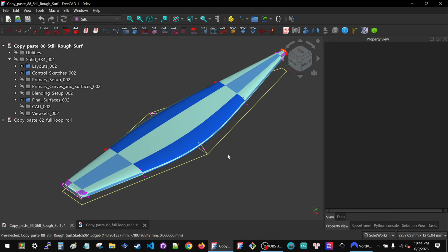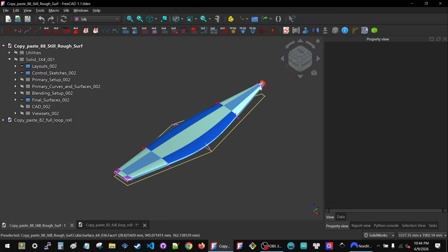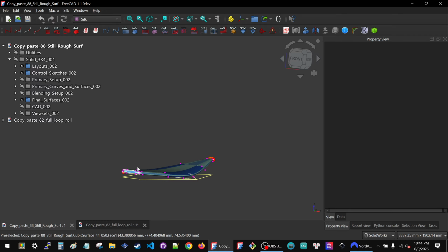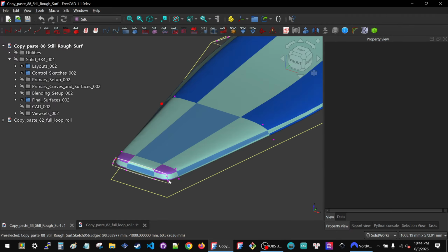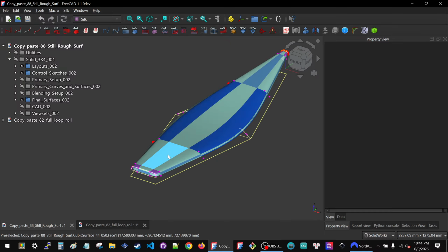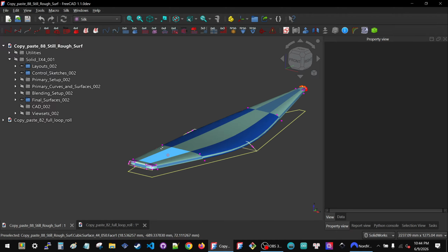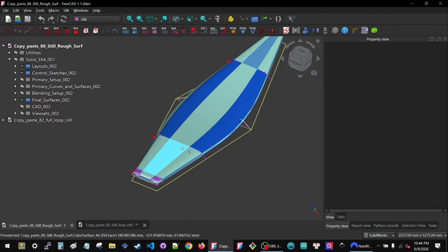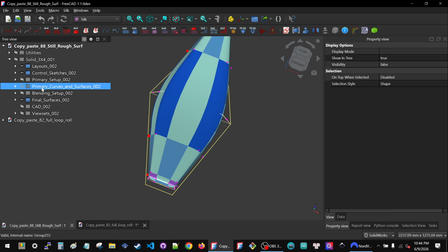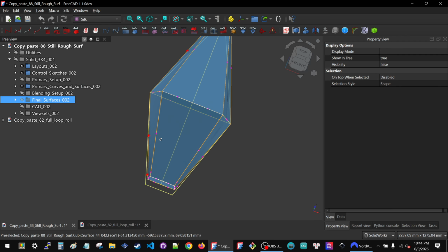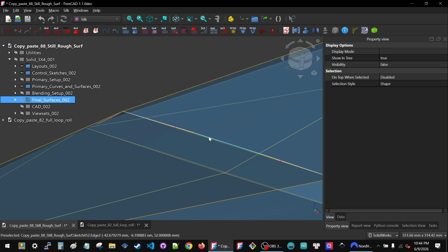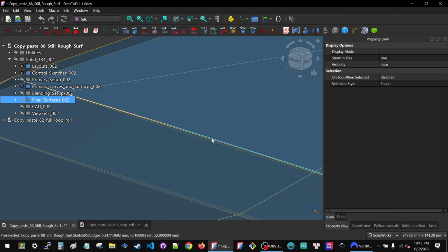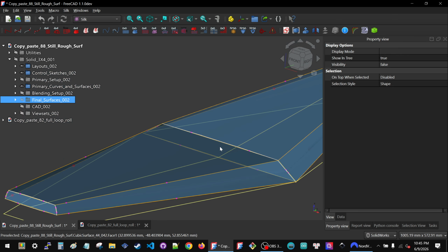Okay, so this is what we got up to last time. We snapped our object to the layout and we reconfigured the sections so that they follow the layout, and we set the last few remaining dimensions. So what else do we need to do? Well, we will need to replace the straight lines here on the spans with curves, and we will want to puff up the curves around the section because they're almost completely flat right now.